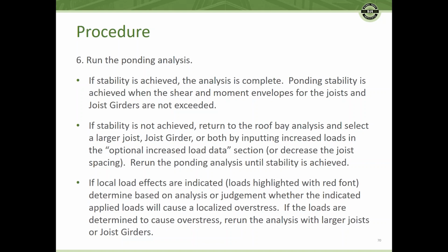As I mentioned before, you can run into cases where the moment and shear envelope checks pass, but you have some applied loads higher than the specified allowable load. In these cases, the design professional will need to determine by analysis or by judgment if the overloads are okay or whether larger joists and joist girders are needed.